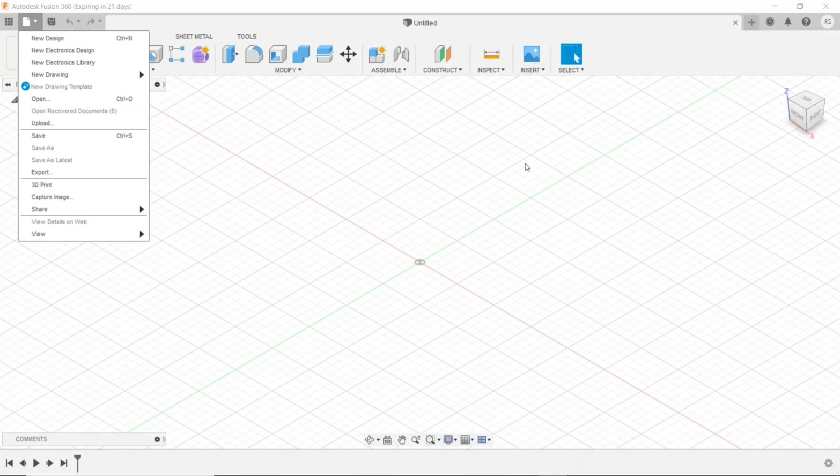When you insert a mesh, it loads it in there with other properties, but you cannot edit that mesh because it's a B-rep and not a T-spline. So you have to edit all kinds of stuff to it to get it to where you can manipulate the file to put CAM paths on there.